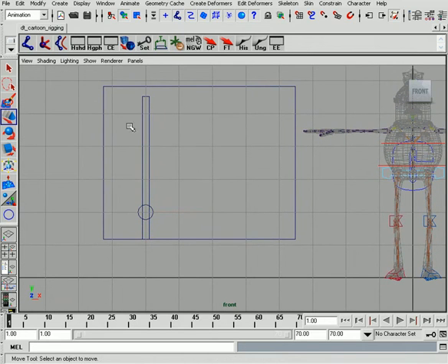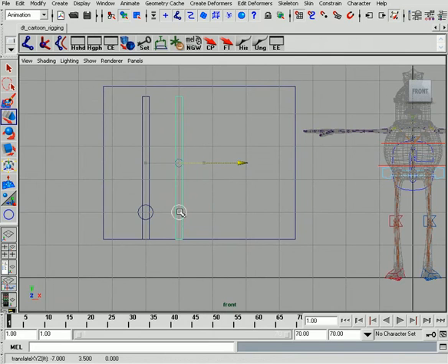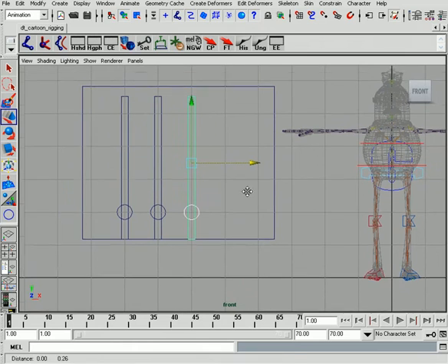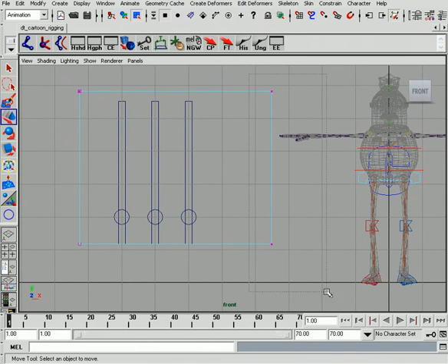So now we can select what we have here, duplicate it, use again the X transform, and just move it over. You can just snap it right next to it. And then again, duplicate our next set, use the X transform, hold X, and move it over again. Alright, so this is looking pretty cool so far. What we can now do from here, if we wanted to, is adjust our window a little bit more, just so everything looks uniform together.